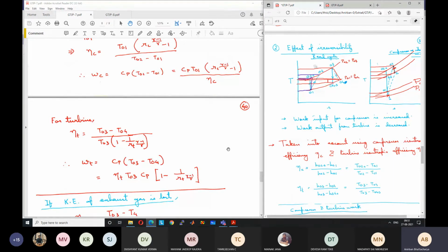Why? What may be the reason? Primary reason for this? Pressure loss. So in case of compressors, lower pressure gradient across the compressor will be present. At each compressor stage, lower pressure gradient has to be present, so that I can have a larger number of stages.